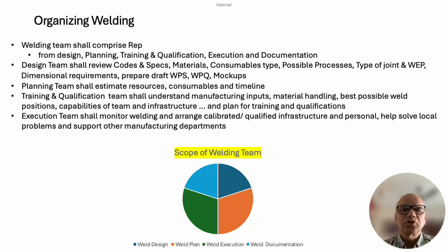Similarly, he has to ensure that when the assemblies are coming to him for welding, or the setup is being done, and he has to provide welders for tacking, the input conditions for him are good. That means the edge preparation is good, the angles are good, root face and root gap have been properly maintained, cleanliness has been done, and NDT on edge preparation, if required, has already been done.